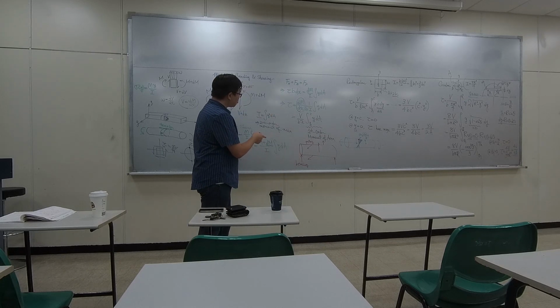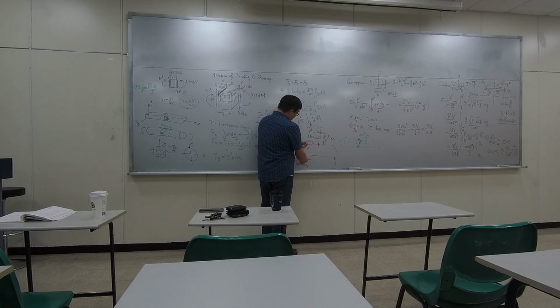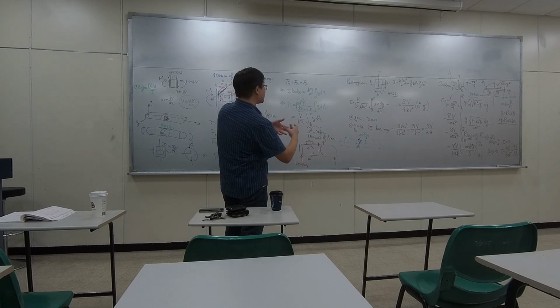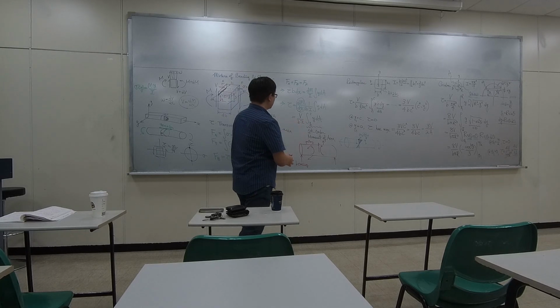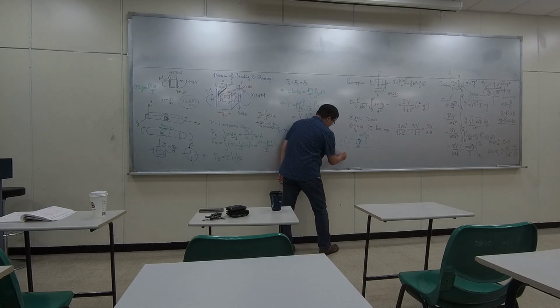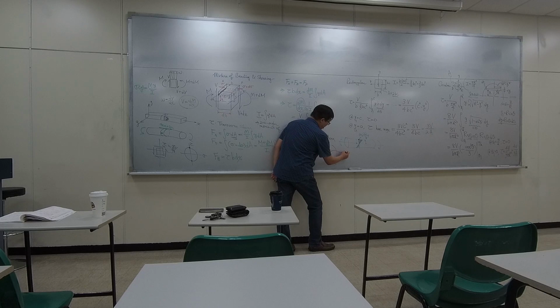So in this particular problem, because the force over here generates, I don't remember which direction, some kind of torque right here, and over here there's another torque. So this geometry is being twisted, torsional shear. And the torque we computed tells you how much shear you have. So the shear stress equals 16T over pi d cubed.